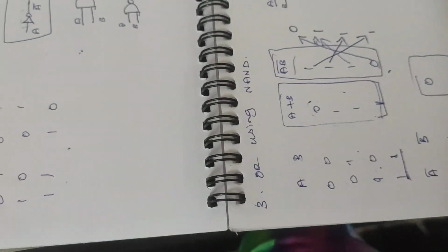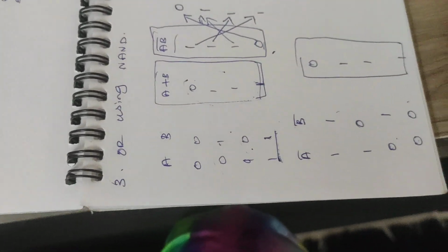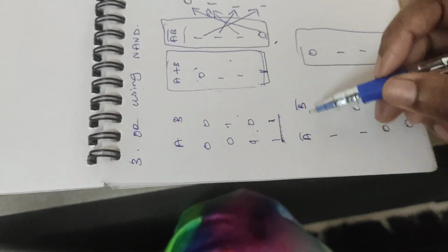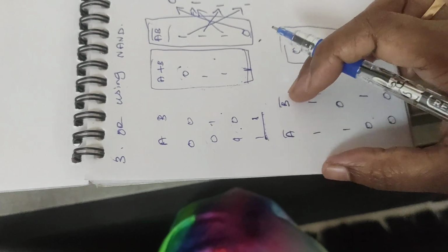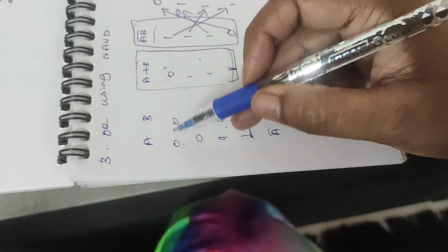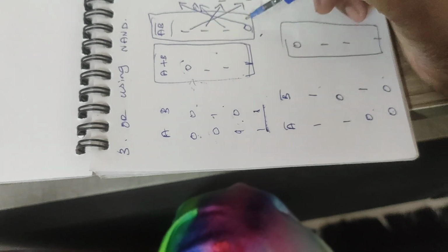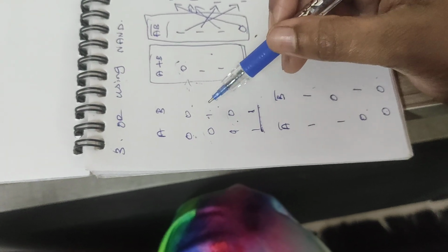Now for the 1 1, what we will be having is 0, since at the NAND gate only we have that, right? So 0 1 1 1. Now this is what we are getting: the expected output of the OR gate we are getting through this one. How have we implemented this? We just inverted the A and B. Only the inputs we are inverting to get the OR gate outputs. If I give 0 0 as an input to my NAND gate, it will give only 1. It won't give the 0.